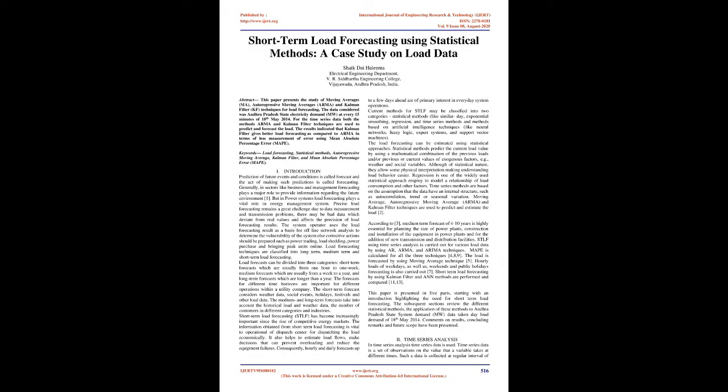Short-term load forecasting using statistical methods, a case study on load data. Abstract: This paper presents the study of moving averages, MA, autoregressive moving averages, ARMA, and Kalman Filter, KF, techniques for load forecasting. The data considered was Andhra Pradesh State electricity demand, MW, at every 15 minutes of May 18, 2014.